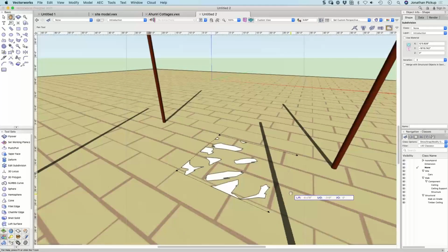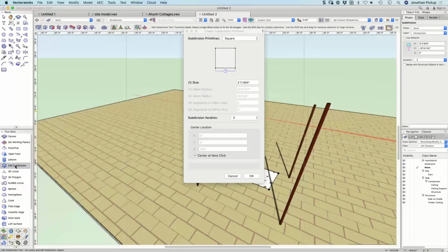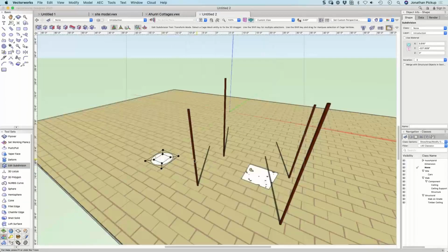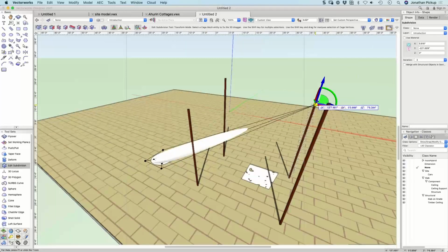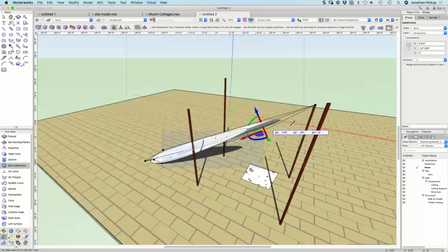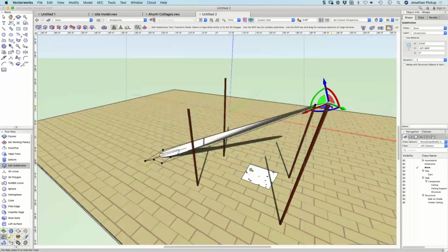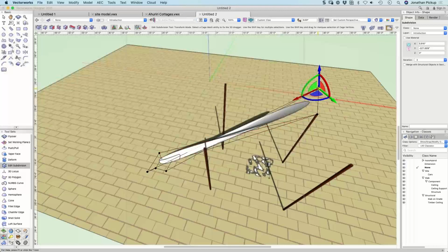An important thing is, if I want to connect those 4 points to these 4 columns, it would be difficult if I started with a circle. So there's my circle object. If I grab that little dot there, click on that dot in the middle, it's turquoise to start with. Then we go to the top of that column, and then we grab this turquoise dot and put it on the top of this column. I'm just using my Z key to zoom in. And you notice that missed it, so let's go back over here. I want to snap to the top of that one. Z key, I want to go to that point there.